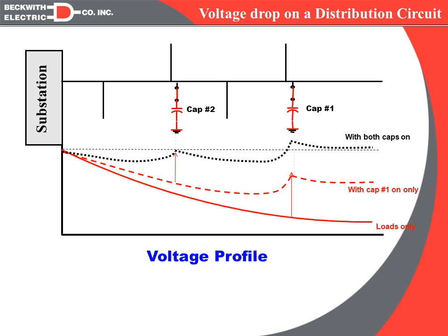Having the voltage lower at the end of the line really does us no good because the load we're saving on is insignificant. So the only way to get the voltage to be lower here is to make sure that the voltage here is at the low end of the overall voltage. And that's what was accomplished with the capacitor banks.